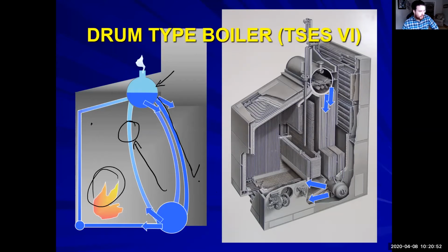your steam drum is half filled with water. Your water drum is completely filled with water. And if your steam drum is half filled with water, do you think you have one-way valves here? Or over here, or over here, or over here? Are we going to have directional valves? No. Wouldn't it just be directed by the difference in temperature? So yes, it's not going to have any directional valves. It's going to be determined on difference in temperature and how all of the liquid moves inside of it.